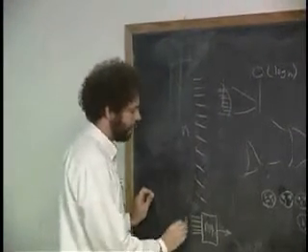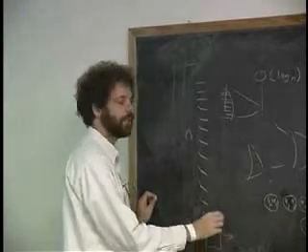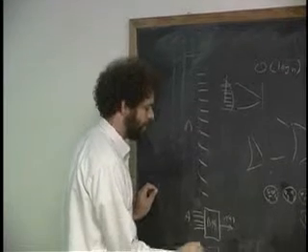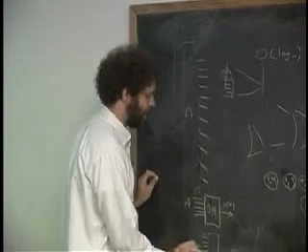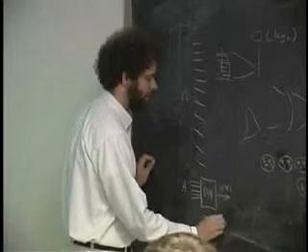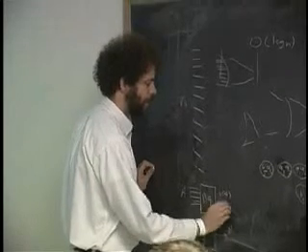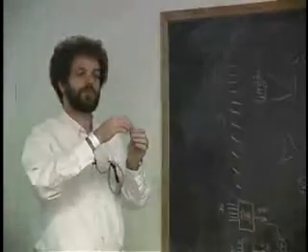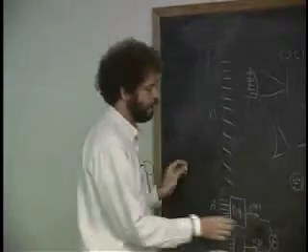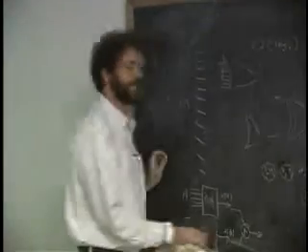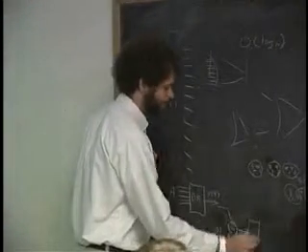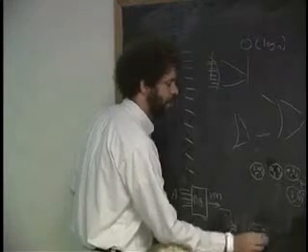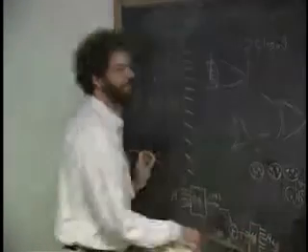So here's A that goes in here, and here's a voltage that corresponds to A. And then I could have another digital to analog converter here that would take B and produce a voltage corresponding to B. Then I could put it into an analog device to sum them, which is similar to putting the 2 pieces of chalk right on top of each other. And then after I got an analog voltage, which was the result, I could put it into an A to D converter, and I could get the sum of A plus B. And don't laugh, because people have actually built this.